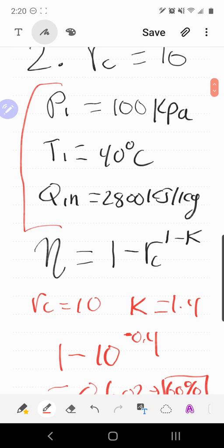And instead you can get the solution very simply with just the efficiency equation. There's actually another one of these that is much longer that you can use if you are using a diesel cycle. Again, most likely it will be in the handbook as well, so you can use it there.